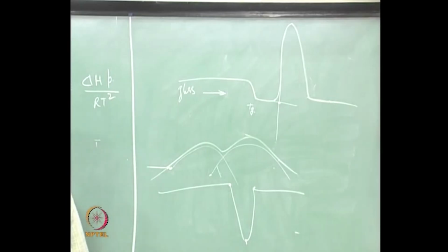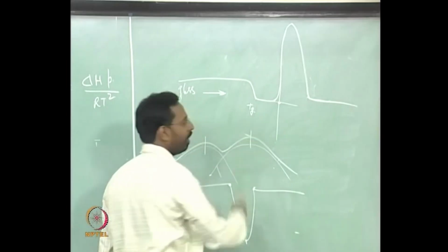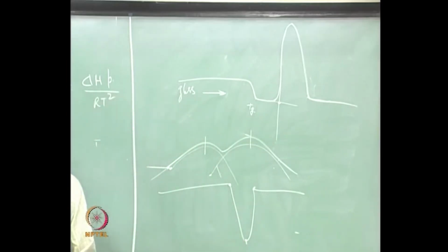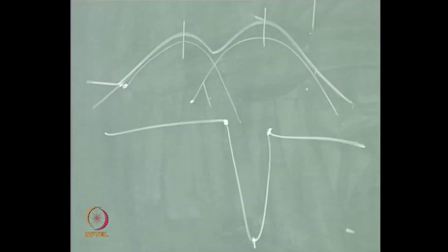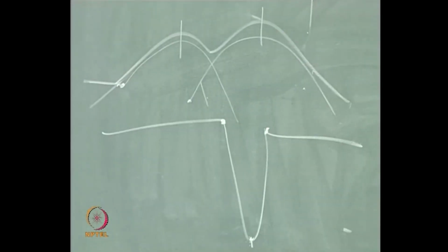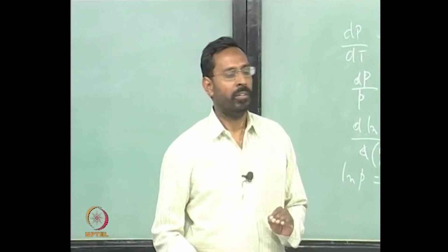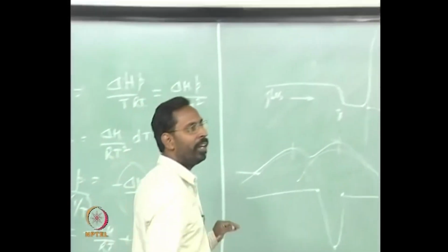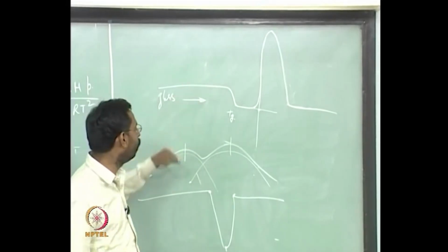Under such conditions, people usually consider the peak temperature as representing the transformation. Though we definitely know the peak is not the temperature where the transformation has started. But in case it is more difficult to find out the onset, we should do this.